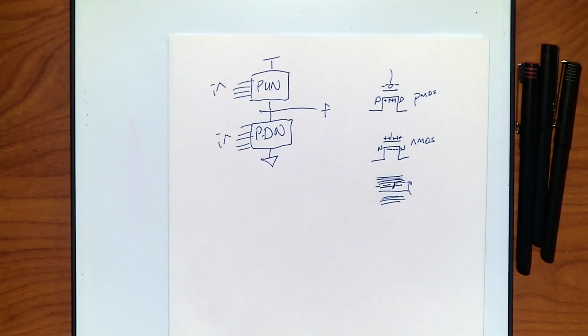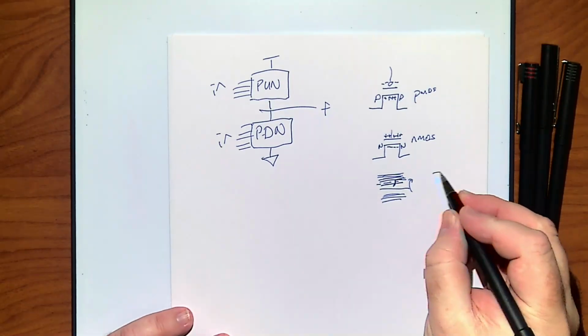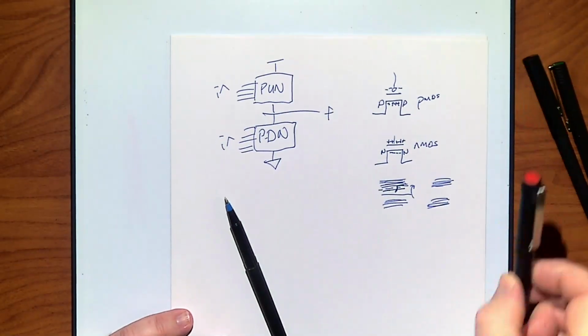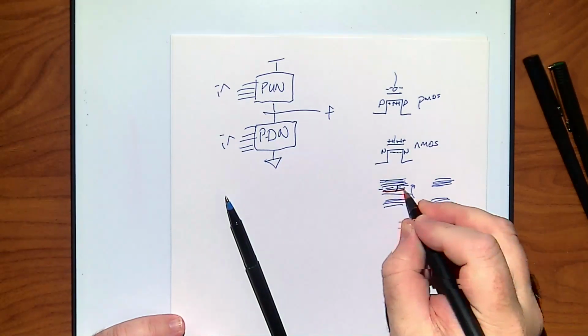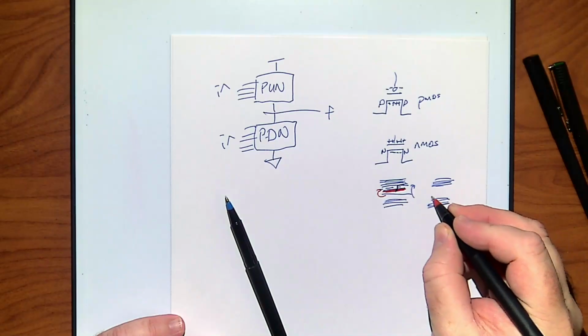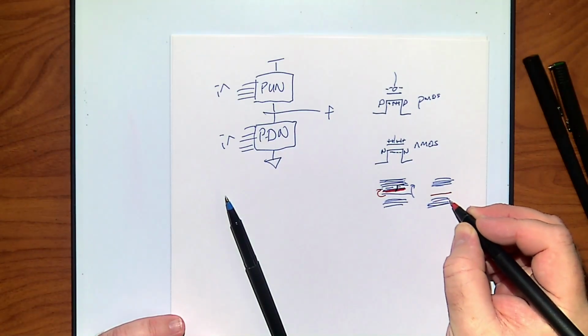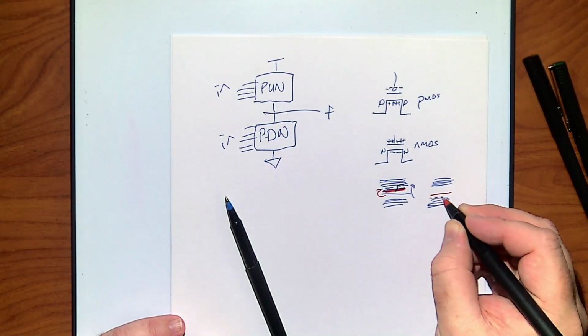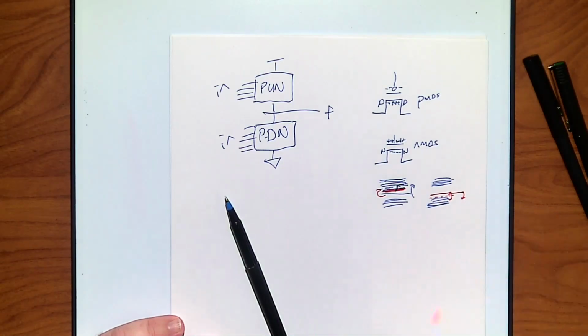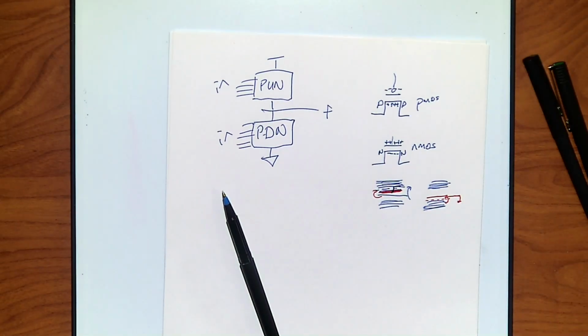What happened when I was doing a P-type material? Again, we've got this and this, and maybe I should do these in a different color. For the N type, I added the new band here and Fermi moved up. For this one, I'm adding a new hole, an empty spot, just above. Fermi moves down, just in between the electrons, and an electron can go up to here, move about, and then fall into the next hole. That makes it look like holes are moving.